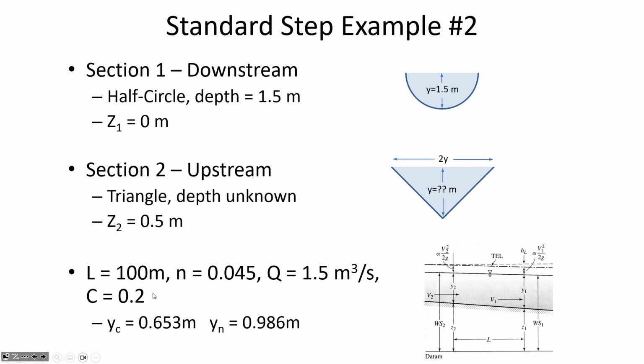1 versus 2, right. Yeah, in the past, whenever we were saying location 1, what we meant was the upstream location, and location 2 meant the downstream location. Here, the way that we assign the number 1 and number 2, 1 is meant to indicate the location where we know the depth, and 2 is the location where we're trying to calculate the depth. And so it's the location of the unknown. So here, in this example, 2 is the unknown, and that's the upstream location. And so let's keep that in the back of our minds as we work through the template file, that 1 doesn't mean upstream.